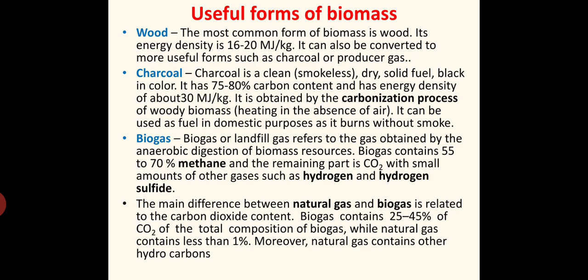You may be getting confused between natural gas and biogas. Actually both are almost the same, but the main difference between natural gas and biogas is related to the carbon dioxide content in it. Biogas contains 25 to 45% of CO2, whereas natural gas has only 1%. So natural gas is a much better fuel compared to biogas. So the only difference is in the carbon dioxide percentage. Of course, natural gas will have other hydrocarbons also.